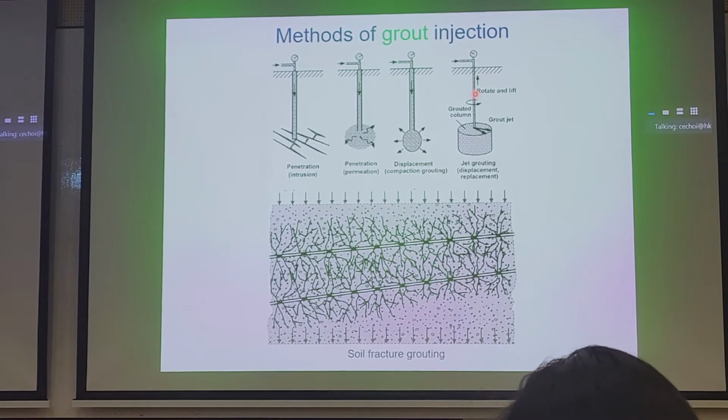Well, there's trade-offs. If you add air and water as you're creating jet grout columns, you're reducing the strength of your columns. You'll see later on that if you use single jet grout mixing or single nozzle jet grout mixing, you'll get the highest strength columns. However, your influence radius of your columns decreases. You can't get very large columns, but they are very strong. If you use a dual or triple nozzle jet grout mixing, you can get a much larger area, a much larger radius for the jet grout columns, but the strength will suffer.